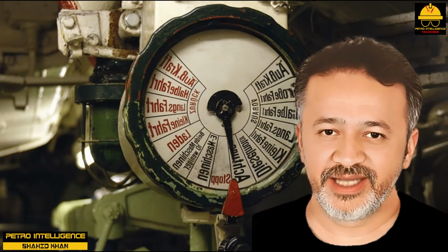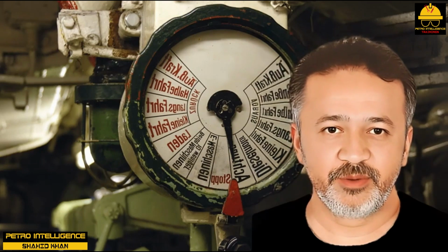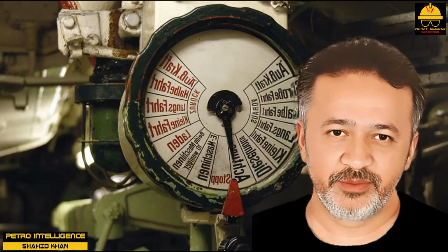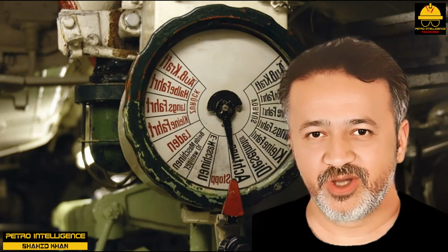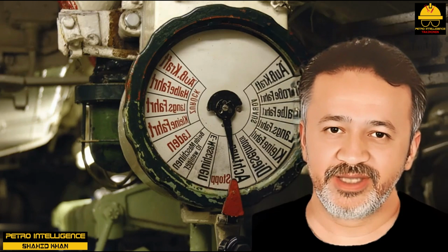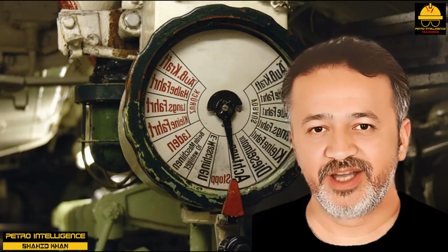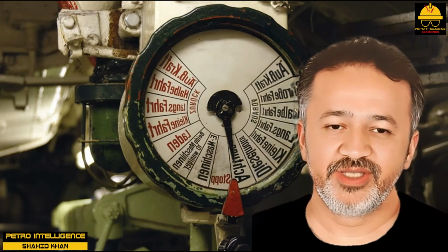Level measurements are identified by a fixed reference point, typically 0, above or below a product. Level measurement devices can be classified as direct or indirect. Direct instrumentation is in physical contact with the surface of the fluid. Indirect instrumentation incorporates pressure changes that respond proportionally to level changes.